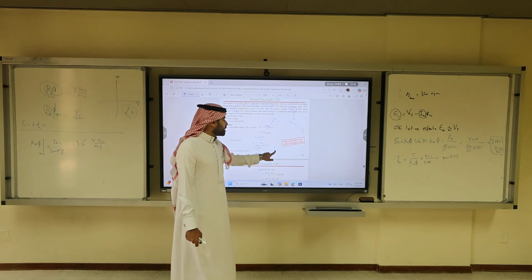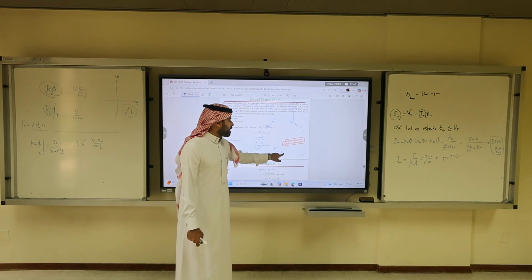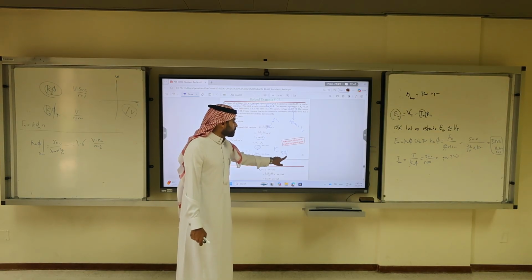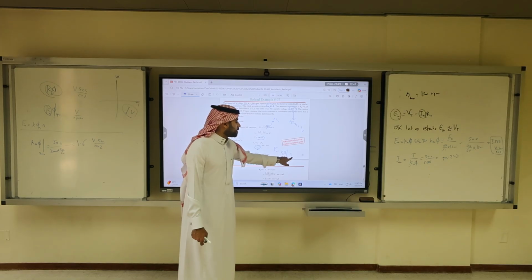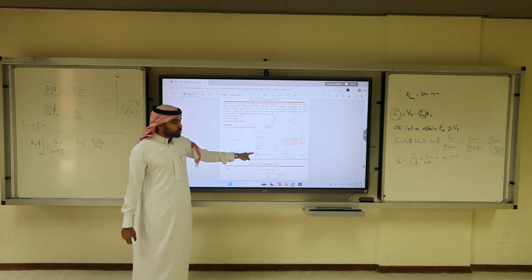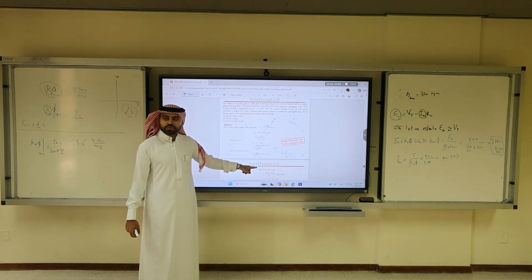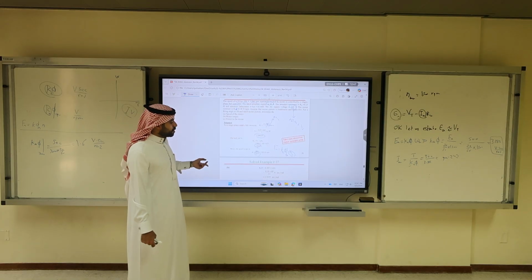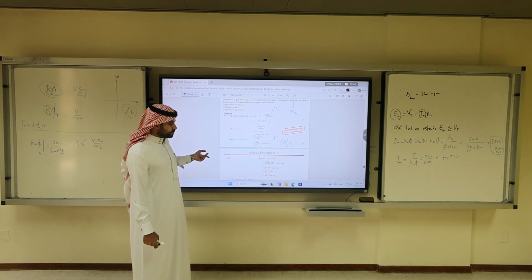Remember the equation? EA equals Ka times the flux, in V per RPM, times N in RPM. So he wants the N. He gave you the constant, you calculated EA, get the N. N is 196 over 0.18. And solve it.